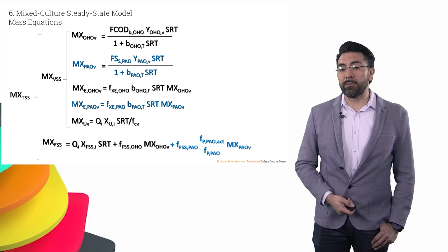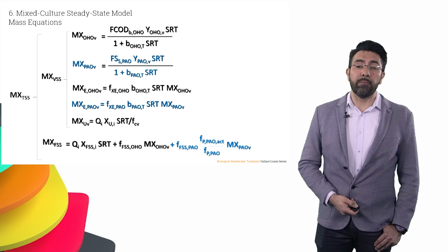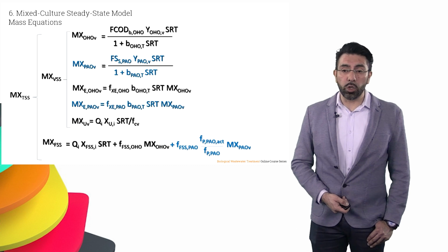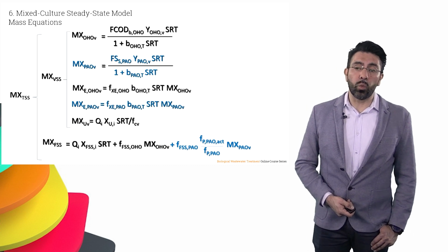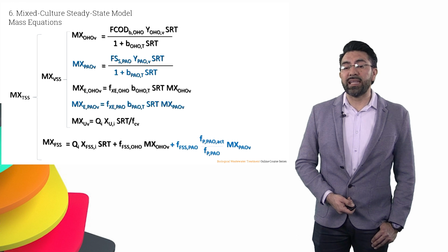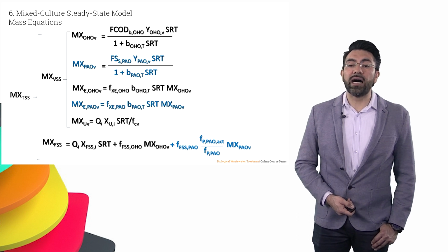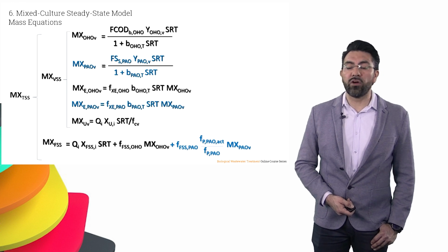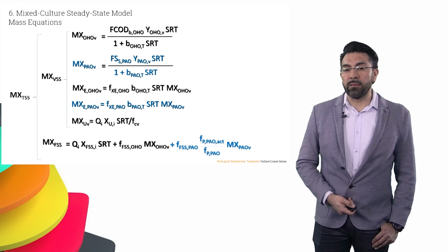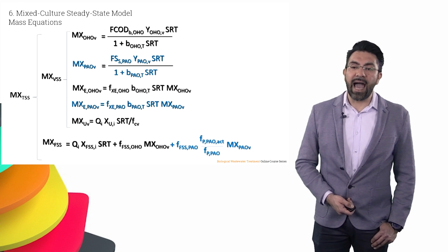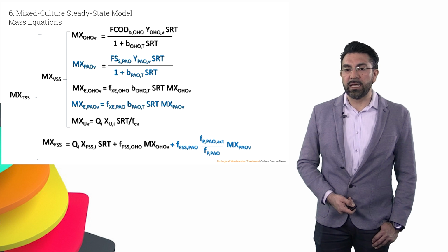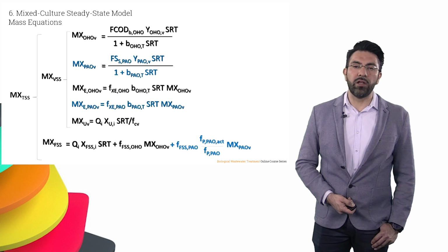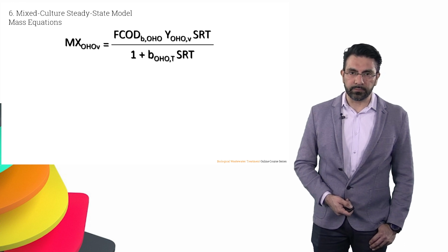For that purpose, we need to estimate what is the amount of fixed suspended solids that the PAOs typically have, that one as a function of the mass of PAOs, but taking into consideration what is the amount of phosphorus that they actually will store with regards to their maximum phosphorus accumulation. Because the more phosphorus they can accumulate, and because phosphorus is an inorganic compound, the higher the amounts of fixed suspended solids that these organisms will contribute to in the system. Let's have a look at each equation separately.